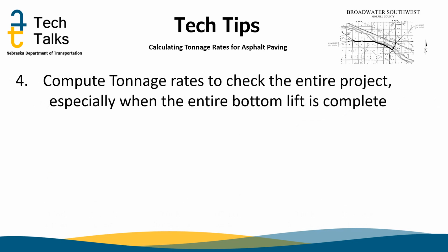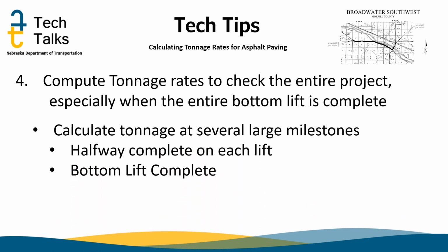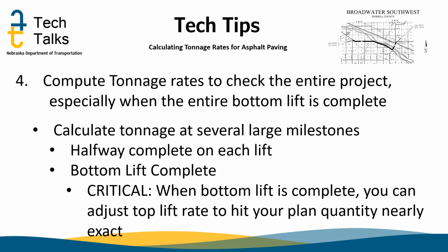Tip number 4. Compute tonnage rates to check the entire project, especially when the entire bottom lift is complete. Calculate tonnage at several large milestones, such as halfway complete on each lift and when the bottom lift is complete. When the bottom lift is complete, it is most important because you can adjust the top lift rate to hit your planned quantity nearly exact.